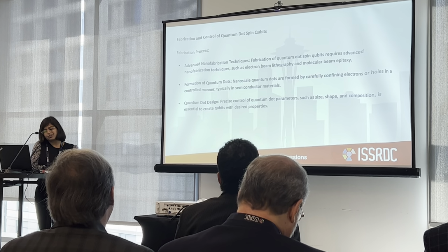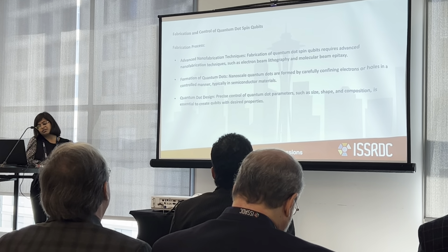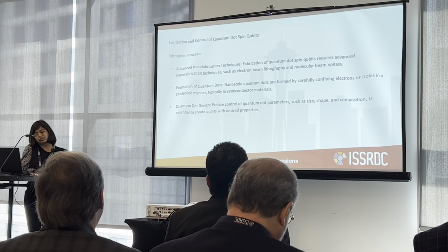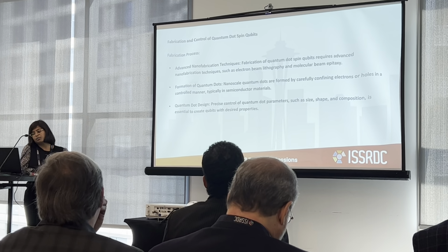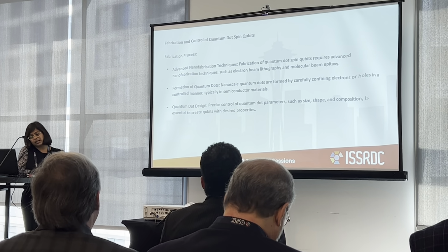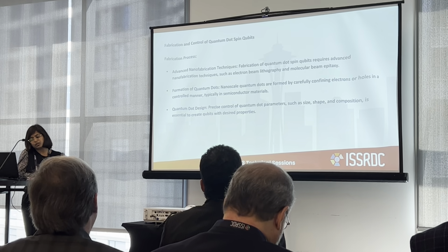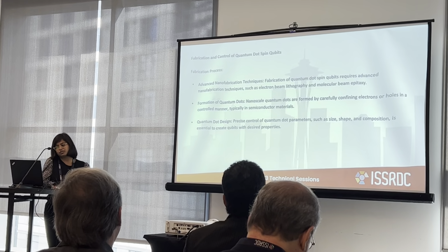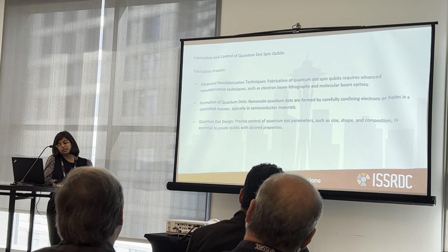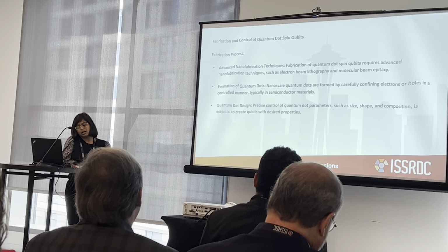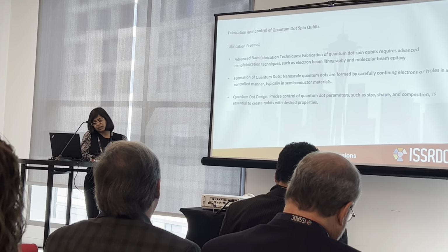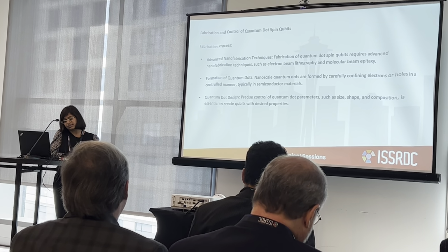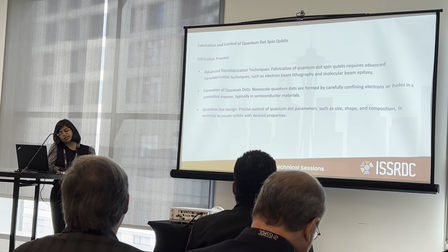Advanced nanofabrication techniques: fabrication of quantum dot spin qubits requires advanced nanofabrication techniques such as electron beam lithography and molecular beam epitaxy. Those are the two main ones. And formation of quantum dots: nanoscale quantum dots are formed by carefully confining electrons or holes in a controlled manner, typically in semiconductor materials. And quantum dot design: precise control of quantum dot parameters such as size, shape, and composition is essential to create qubits with desired properties.